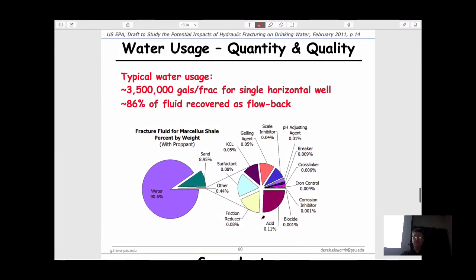the agents which are used to wash proppants into the fractures. You pump up the well bore, it drives a hydraulic fracture, so when you back off the pressure, it doesn't just deflate and close. You wash sand into it as proppant, and you wash that sand typically with water, but also you put in some other things. The other things are things like bactericides to stop bio growth in the subsurface. There are things like friction reducers that make it much more slippery, so that the pressure that you apply on the well pad at the top of the well actually gets its way down to the bottom.